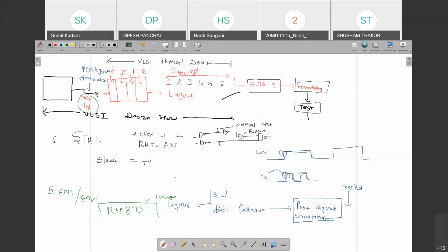We have to pass our design for this checkpoint also, and sub steps as well as these are the abstract steps: partitioning, floor plan, placement, routing. But in detail, we have pin assignment also and many other clock routing, detailed routings. We have to pass through all these steps as well as all the checkpoints, and then we can say yes, this is our final layout.